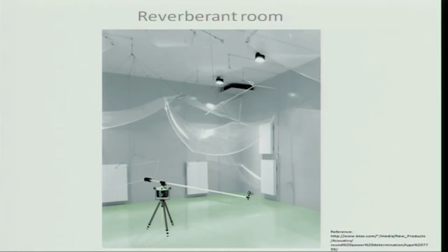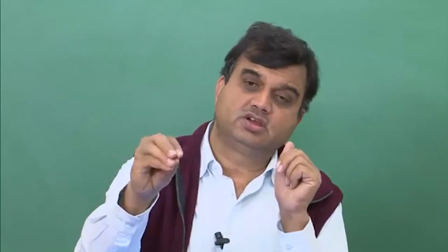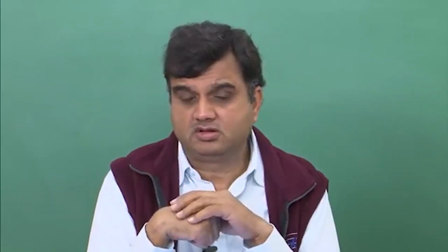Couple of things about reverberant chambers. First thing is that their walls and doors and all the surfaces which sound strikes are extremely hard. You try to make them as hard and as rigid as possible, so whenever sound hits, it comes back and doesn't get absorbed a whole lot. So that is the first thing.